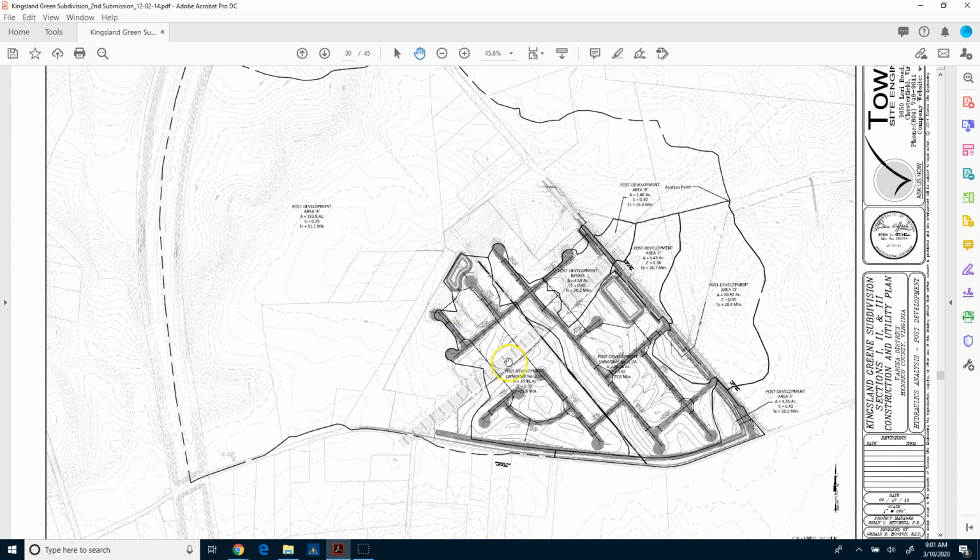And then when you start to add in roads, which are impervious, you add in buildings, houses, where the water is going to run off the roof into the gutters and then into the road, and the road is going to go into the storm sewer, and that storm sewer has got to go somewhere. Well, to keep it simple, the volume of water and the rate at which that water runs off cannot be higher or lower than it was prior to the development. So you have to make sure that the same amount of water runs off the site and not more,